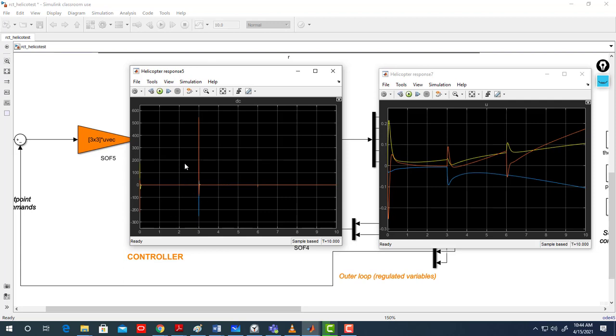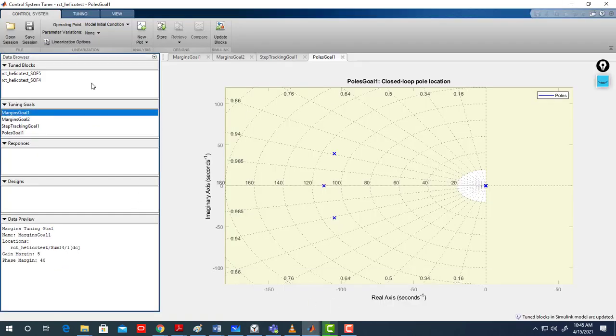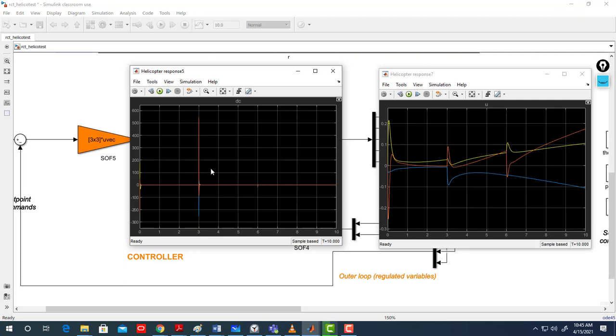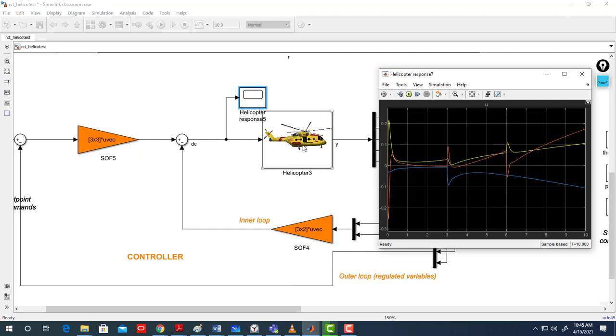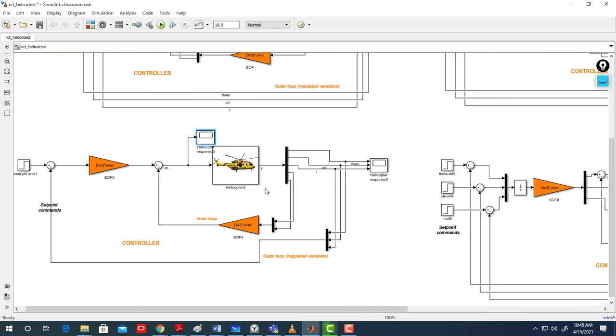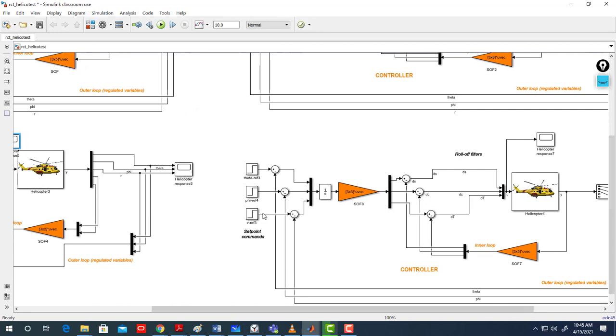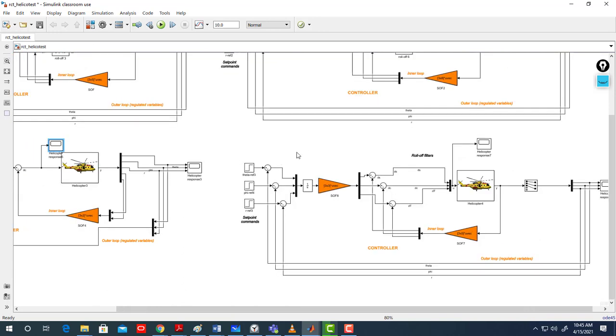So in order to have this stability, you need to have a good control effort, which is not the case here. Even so, I'm applying the same control goal on the Control System Tuner app. I'm taking the same design goal for all. So you see the control effort here is much better. That's why it's not recommended to consider it for that type of system, but for other systems that are really type 1, you go over it, and so now you know how to go on it easily. From now on, if you wish, you don't really need to do pole placement and so on. Do it on the Control System Tuner app.